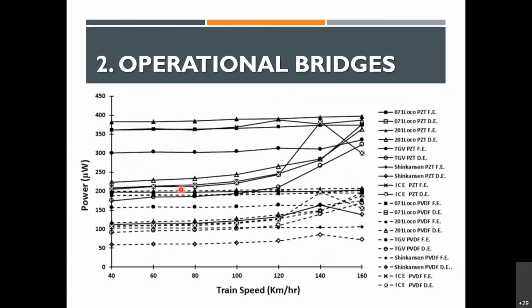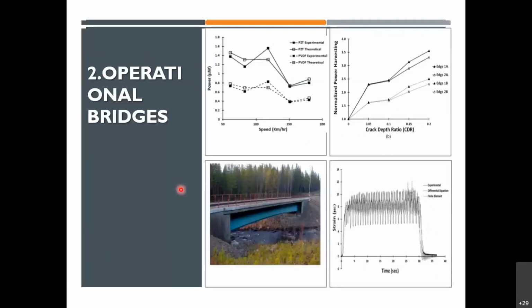Because in and around the peaks, you'll get higher amplitudes, higher power, but it will be very sensitive. On the other hand, if you're on the flat part of the dynamic amplification, then small changes wouldn't matter, it would be more robust, but it would be less detectable. The power levels would be much lower. And at those power levels, the electromechanical coupling is more uncertain. So there is a trade-off here.